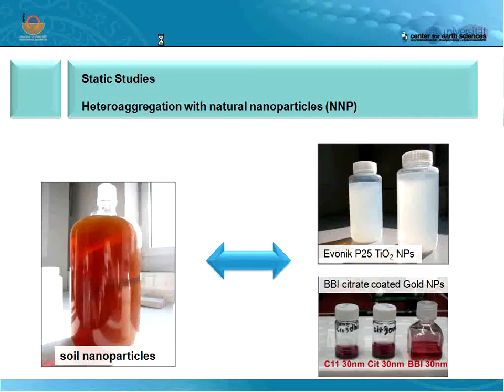We take this bench test and measure the water quality parameters, the hydrochemistry of our natural water, and then we can relate this to each other and somehow predict how this particle will behave in the natural system. The problem is we used filtered waters. And that means there is no suspended particulate matter in there, because we wanted to see how multiple and complex hydrochemical parameters would act on the particles.